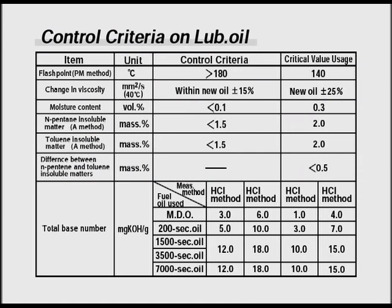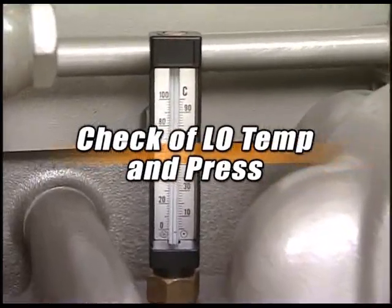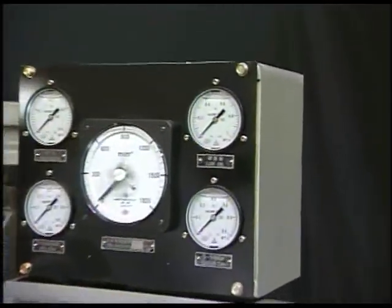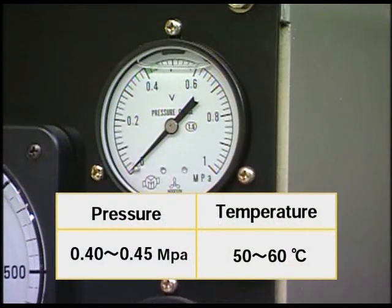Analyze the property of lube oil after every 500 hours of engine operation. Exchange lube oil based on the table. During the engine operation, check that the lube oil temperature and pressure are within the specified value that you are watching in the video. If they are out of specified value, try to find the cause and take appropriate measures.